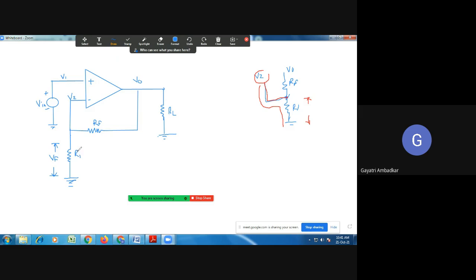So this is our amplifier. What is sampled from the output? The current is flowing and the voltage is developed across R1. So what we have sampled is voltage, and it is present in the input part. If you see the input loop, it is in series. The voltages are mixing, so it's a series mixing.